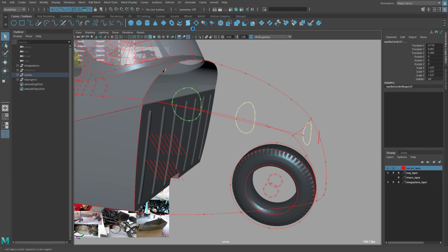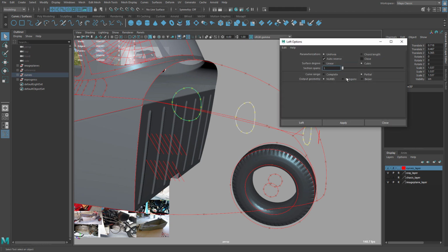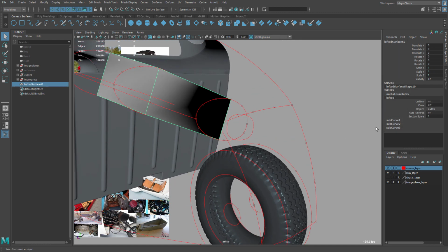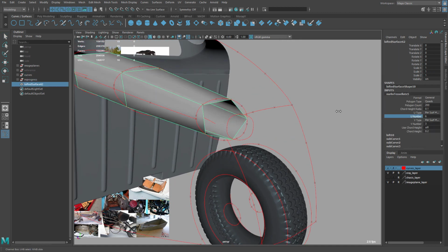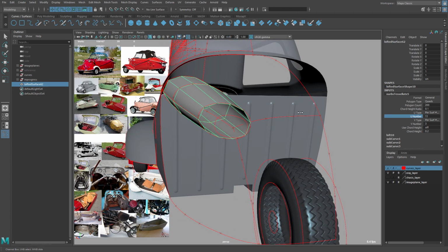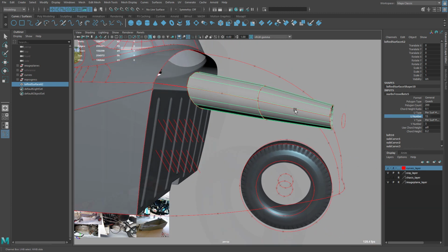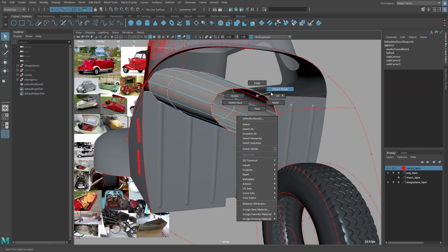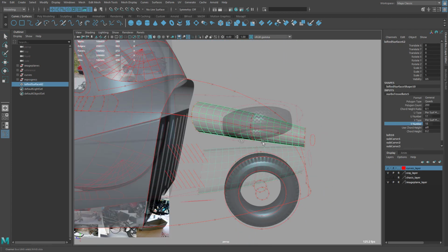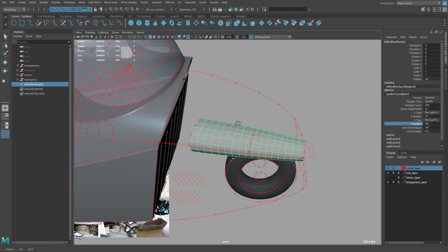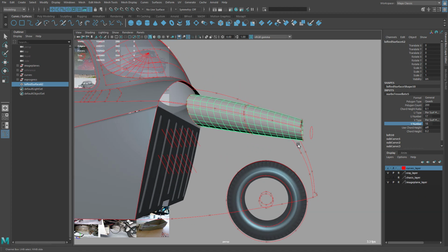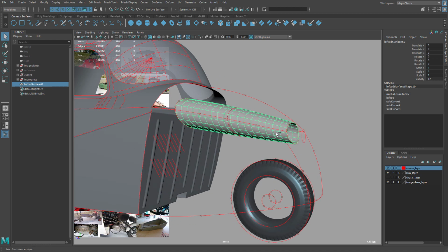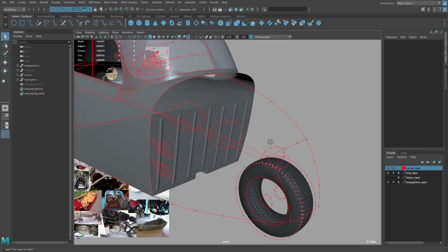Let's look at the settings for the loft here. NURBS, let's go straight to polygons, apply, and then in the tessellate options we can increase or decrease. And I'm not sure how many I'm going to need this way, so I'll just add a little more than what I need. So this shape is done. You can hide it for now.